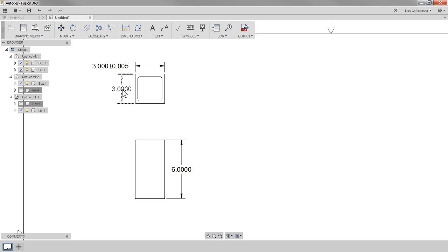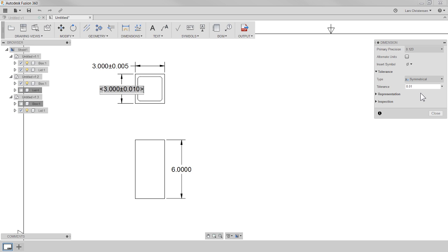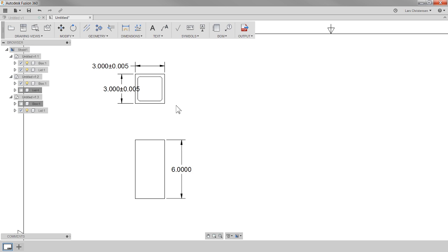And we will do the same thing on the rest of the dimensions. We will go in, we will add some kind of tolerance here on the outside. Let's just make it again 5. And we are telling people who have to make this part that this is what we're going to be measuring when you give us the part and say that it's done.